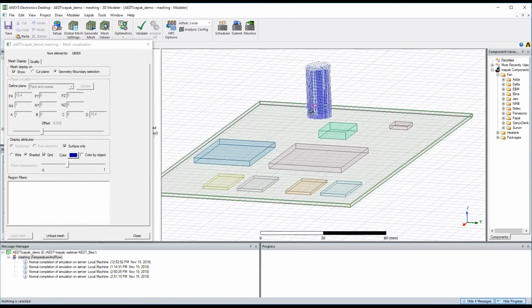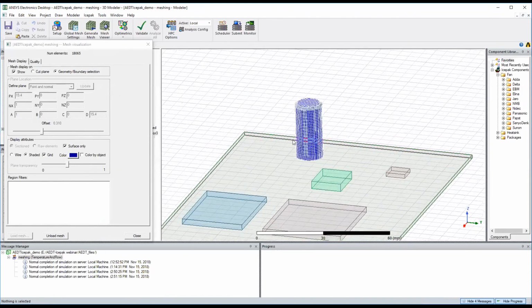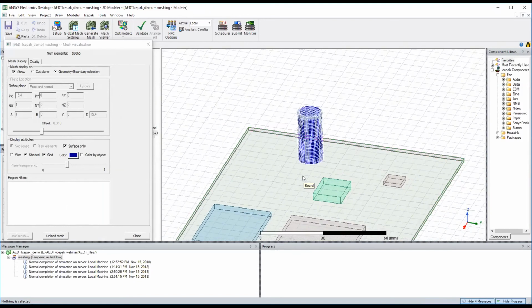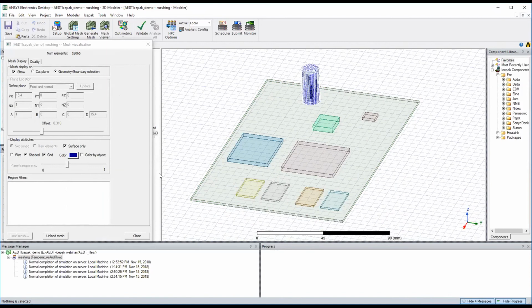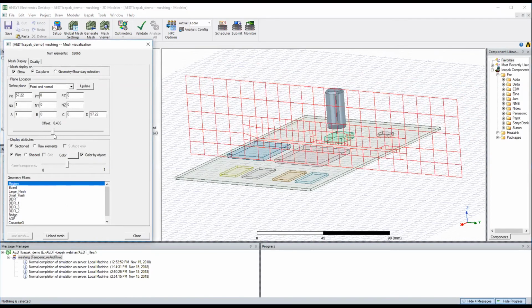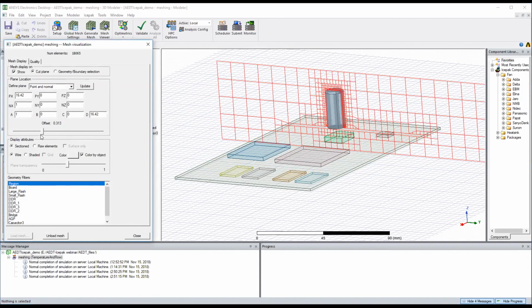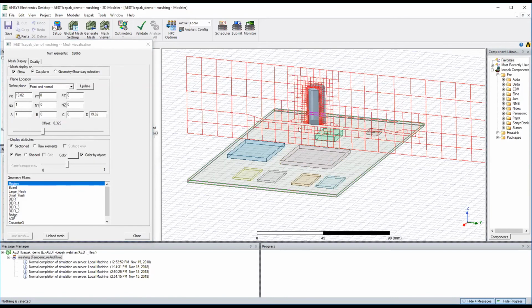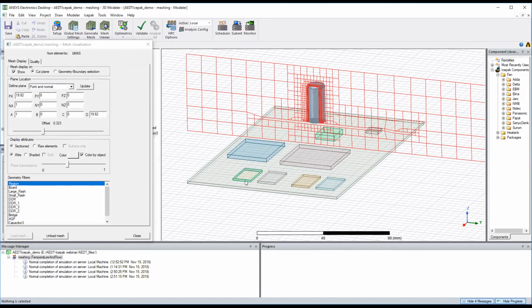You can definitely see now, there's a residual selection here of that capacitor, and most definitely a difference in terms of the mesh sizing that results. If I look at the cut plane through this, you can see cut planes, I can always dynamically adjust where that plane is going to be. You can see there's automatic mesh settings, knowing that these are all actually CAD objects, and here none of them have really been, I don't believe, simplified into primitives yet. You can see the multi-level meshing that's being used to try and capture the cylindrical shape of that capacitor object.